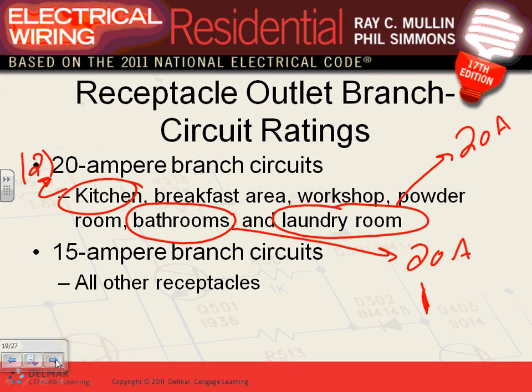Later on, Zach, we haven't talked about equipment yet, have we? We haven't talked about equipment like a dishwasher or garbage disposal. Let me give you a hint. All equipment, 20 amp circuit unless it takes more. Don't use 15 amp circuits with equipment. For equipment, it's a very good idea to use 20 amp circuits. And when I mean equipment, I mean a pump, garbage disposal, dishwasher. Give me another. Exhaust fans. Major exhaust fans, like not in the bathroom. There's an exhaust fan in that apartment building, right in the utility room. You're going to see it. So unless they tell you otherwise, it's 20 amp if it's equipment.